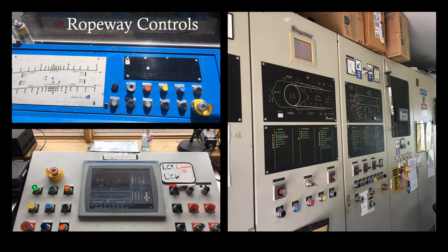Although the specific layout of the controls may look different for all of these lifts, the overall function is actually pretty similar. You will have two stop buttons, a normal stop and an emergency stop, a slow, medium, and a fast button, and a start button and a reset button. If a lift is stopped, the procedure will be to pull the stop button back out, get a reset from both terminals to reset the stop or fault, and then hit start at the drive terminal.